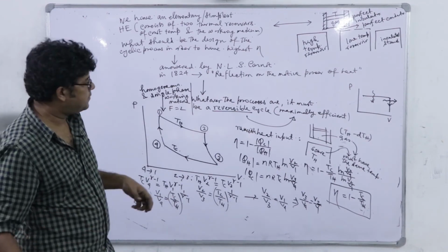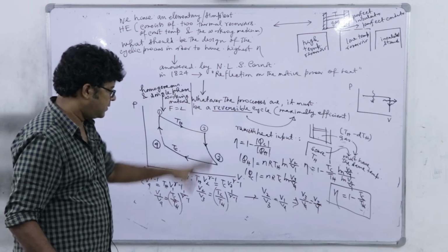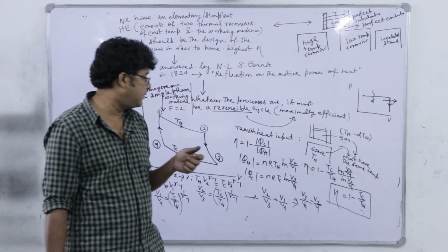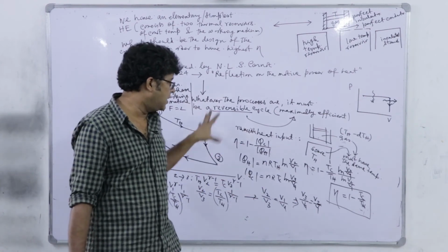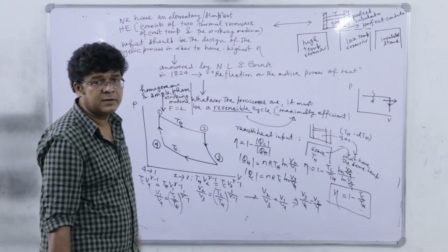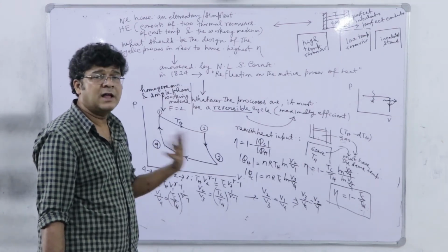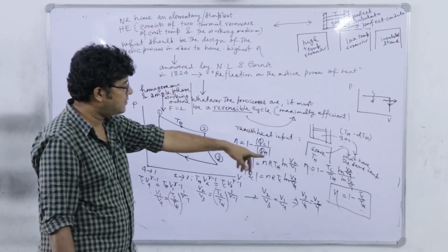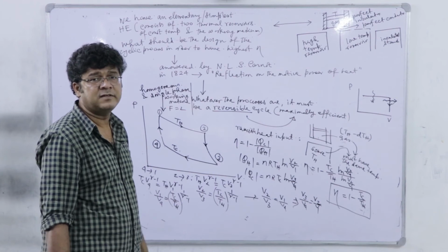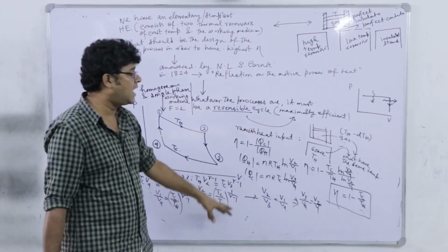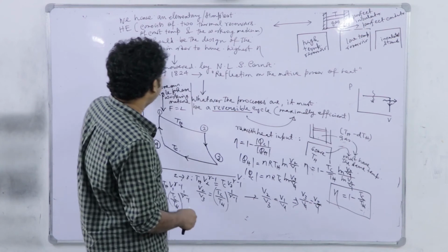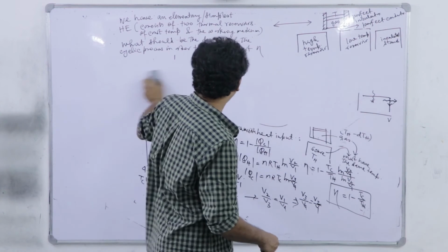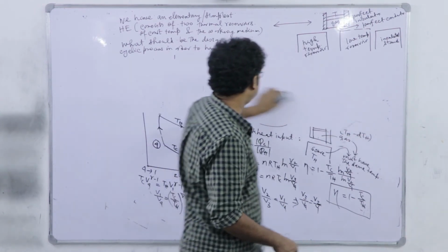So you see that this is the universal expression of Carnot cycle efficiency, and actually it is independent of the working material. We will prove it, but with this limited scope, we cannot prove it in PV space. Once we introduce the definition of entropy, then we can establish that the expression and the Carnot cycle performance are independent of the working material. We do not have to go by ideal gas. We will prove it later, but here we have to think of a certain limiting value, right.